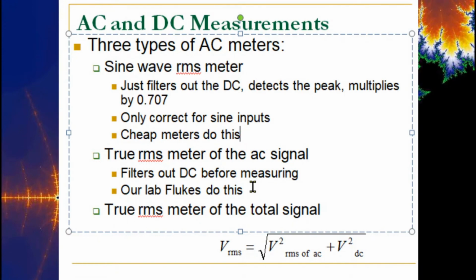Okay, so those are really the only capacitors they need to measure, and the only time they really need to measure current as an HVAC technician is the flame sensors, and they're down in like the 400 microamp range. So they don't need something that measures 10 amps, because they're never going to measure anything like that. They need something that has a very specific low range current where they can measure their flame sensors. Need to have a capacitor measurement on it, and then AC voltages, right? So that's the main thing that they're looking for. And they also use DC if you have a control signal, okay?